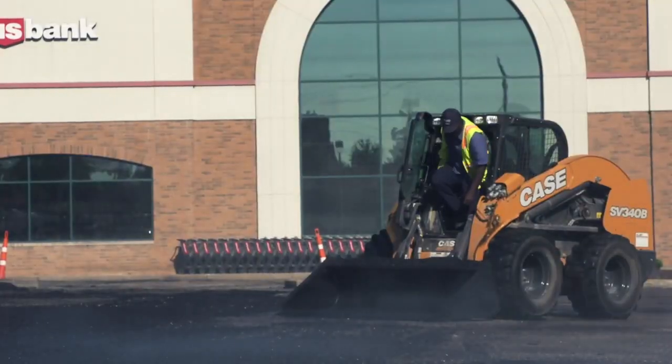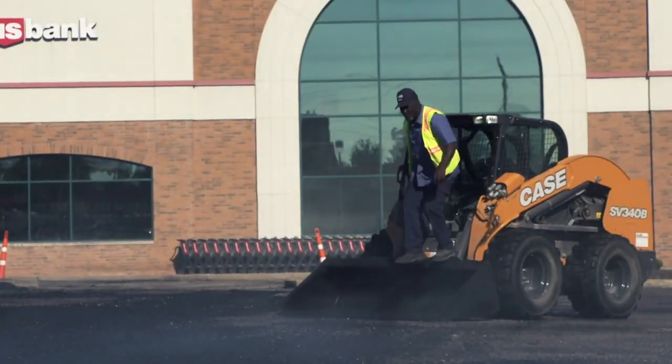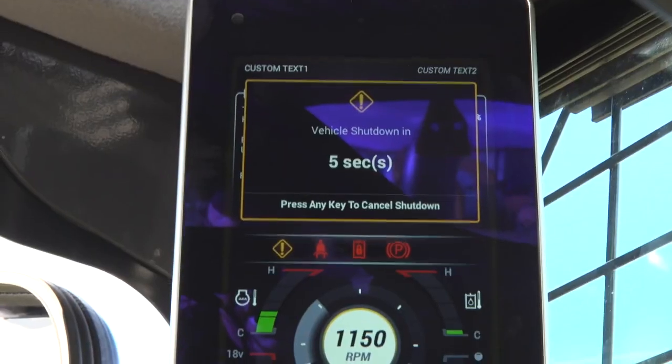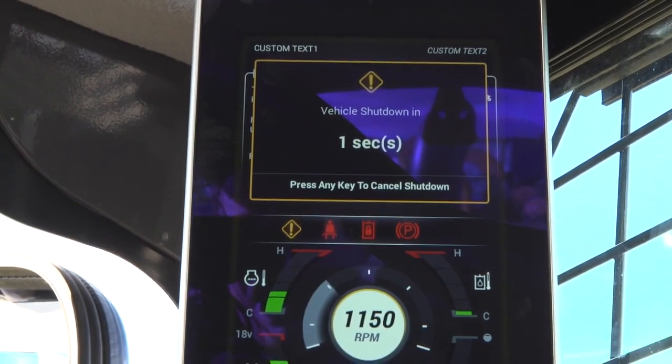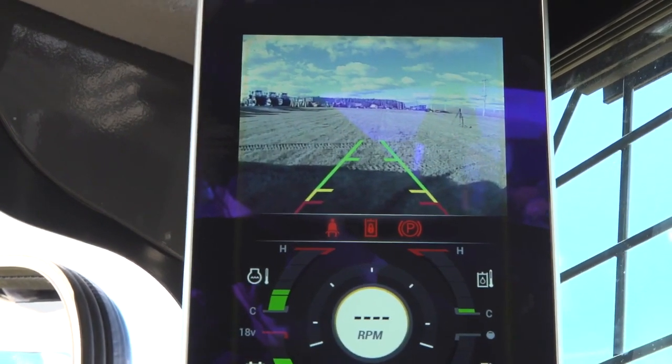Years ago, many of us would idle machines all the time; it was a normal routine or practice. Today, with the new machines' emission systems, it's critical that you have higher exhaust gas temperatures to make these systems function properly. So consider that this can help extend the duration between maintenance intervals of your emission system. Obviously, we can't all forecast when these machines will need that maintenance based on everybody's operational behaviors. So it's important for you to practice this, and that'll extend that duration between those.